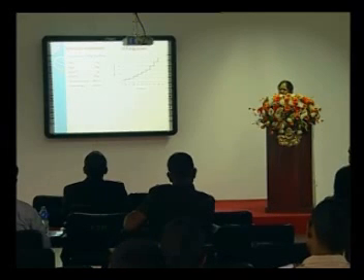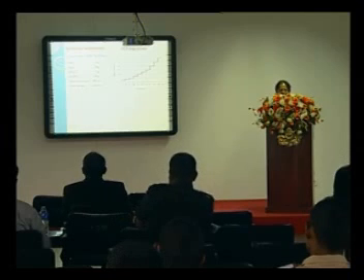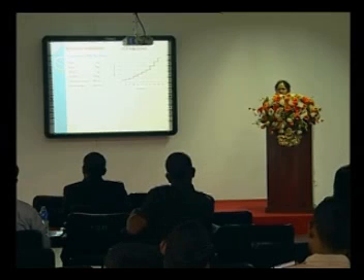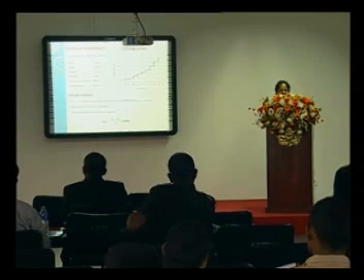We increased the loading rate in 12-day intervals, and collected samples at the end of each 12-day period, from the influent and effluent of each wetland unit, and then analyzed them for BOD, total suspended solids, fecal coliform.